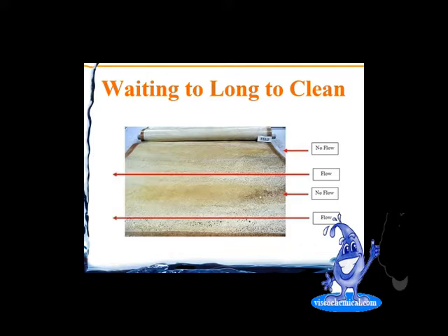Well, that might work if you clean at an early stage, but if you clean at the point where it's channeled, then there's no way, because your cleaning solution is going to take the same path as was taken during normal service. It's going to take the path of least resistance, which is not going to be in the plugged areas. So it could take hours and hours and hours and even days of soaking and circulating to be able to get this clean back to near new performance.